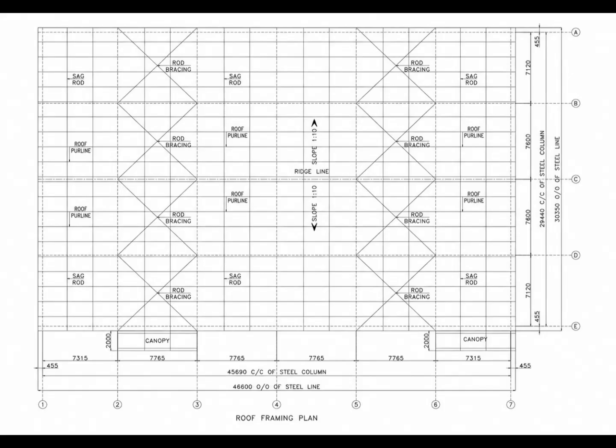Now look at the labels around the sag rod locations. We can see roof purlin labels in the roof framing plan. The sag rod indications are located within the roof framing arrangement alongside these roof purlins. This gives us an important visual relationship. When reading this drawing, we should identify the sag rod together with the surrounding roof purlins rather than looking at the sag rod label alone.